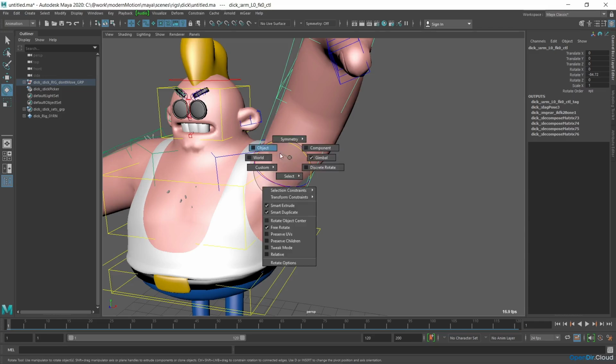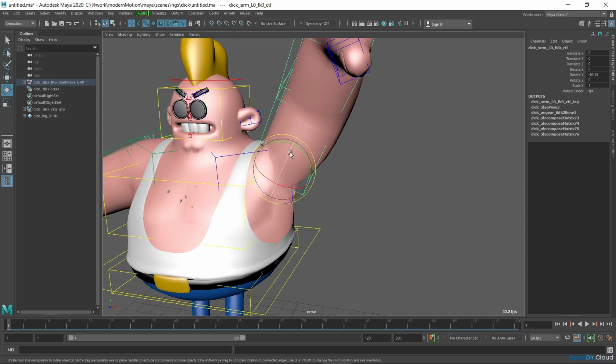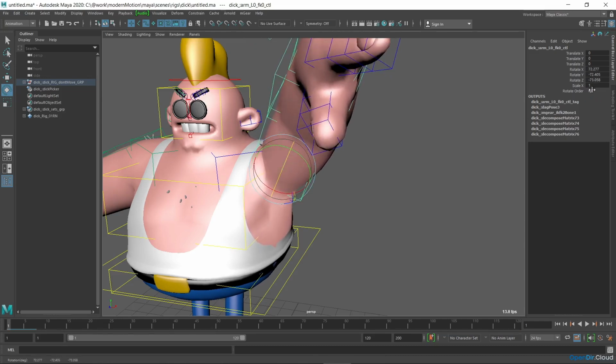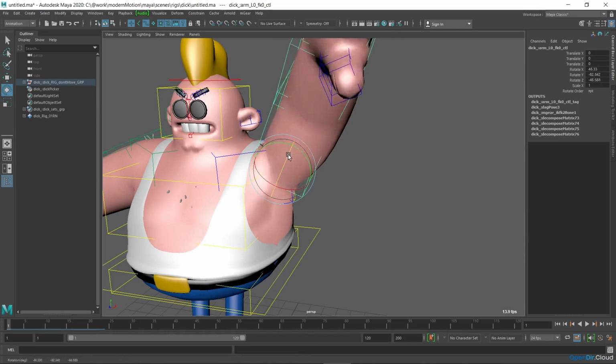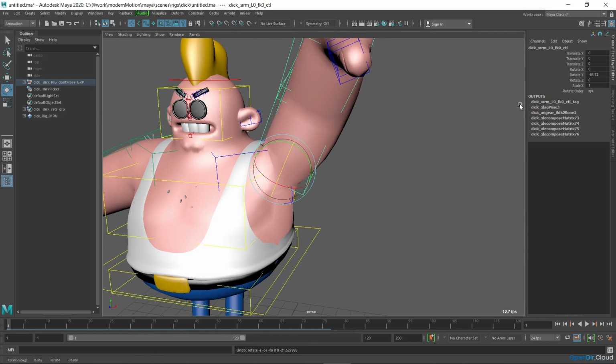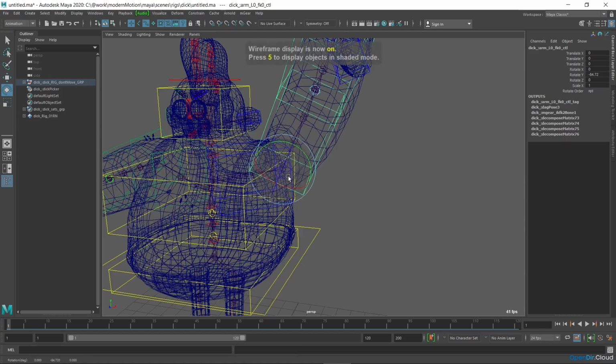Obviously, you can choose a different manipulation mode and rotate the controller as you want, but the rotation will affect the values for all axes at once. As a result, it would make it difficult to edit the animation in the graph editor and lead to strange interpolation movements. In order to avoid this, you need to use the second layer of rotations, which gives an additional controller.